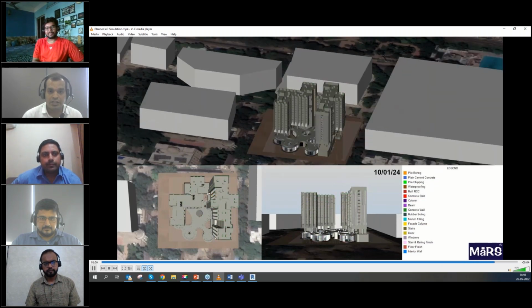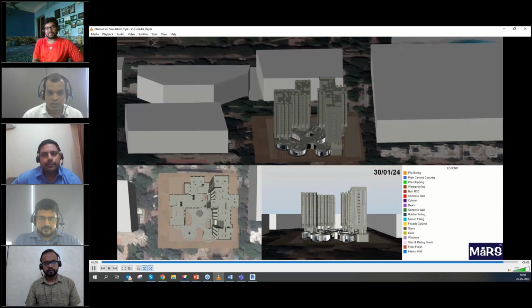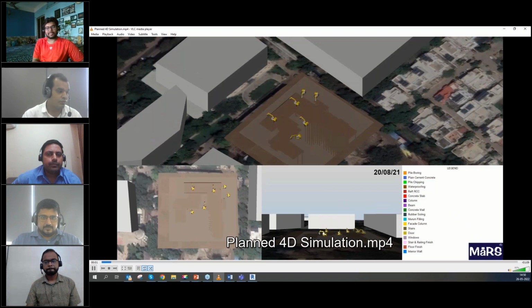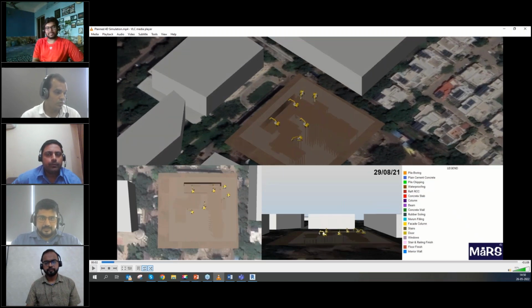So yes, this is one example of a project where you can have the digital information for the entire project. The overall process implemented is, generally, we first create 3D BIM models, then we can straight away use Synchro 4D to use those models directly. We use the schedule provided by the contractors and dump it into Synchro 4D, where every single element in the model is linked particularly to the Synchro 4D platform.